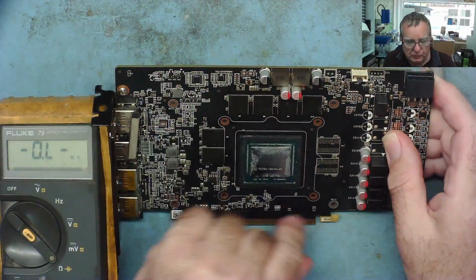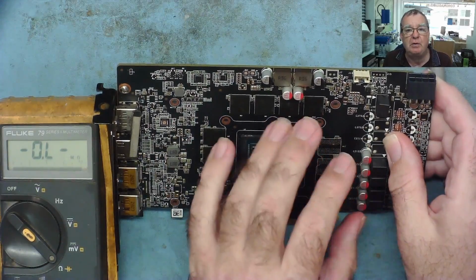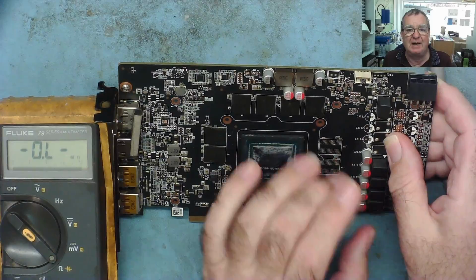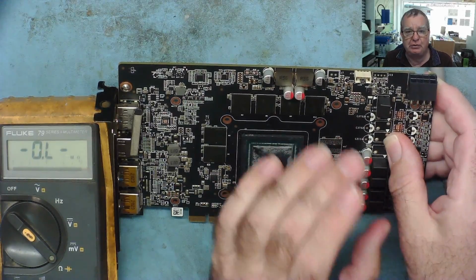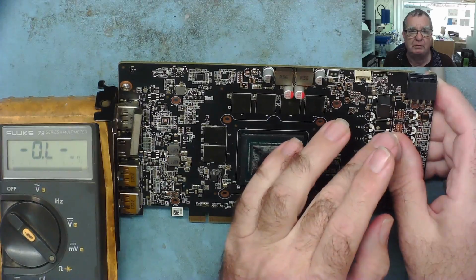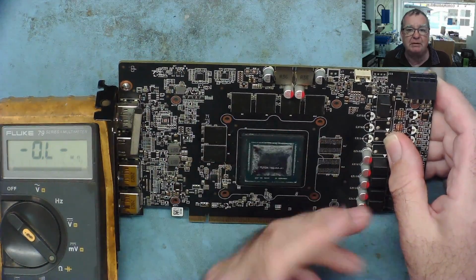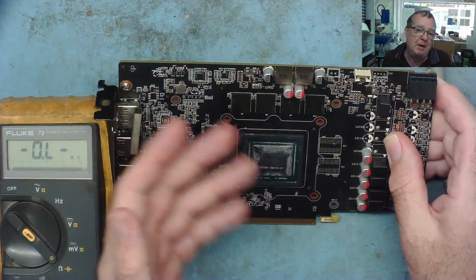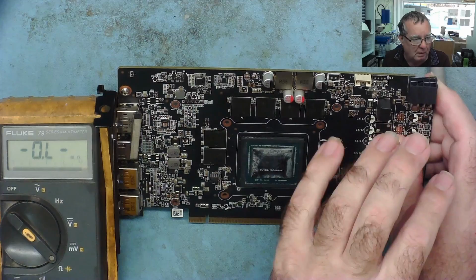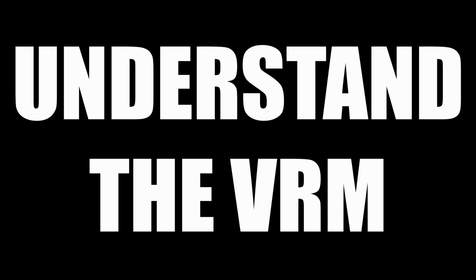Now let's have a close look at these circuits. I'll draw it out and I'll show you exactly where in the circuit the short actually is. This is not a short to ground. This is a short from the 12 volts coming in to the voltage rail that supplies whichever component, whether it's V-core, VRAM, PEX, memory controller supply. It's a short from 12 volts to there. It's not a short from that rail to ground.